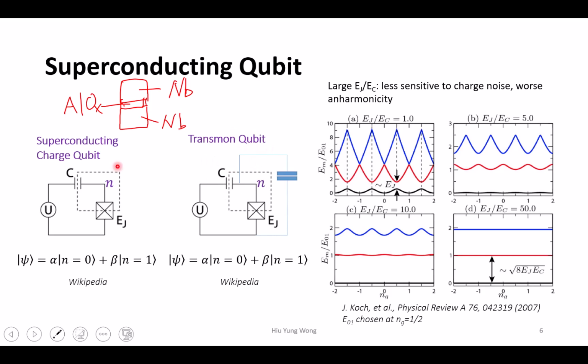What is Transmon? Transmon is basically just like a regular, what we call the Cooper pair box, the so-called CPB. Right, this is a box in which we can put Cooper pairs, but we just add very large resistance, very large shunting capacitor. So what is the goal, right? We don't really understand this figure at this moment. We will learn it. But basically, here on the x-axis is something called the background charge, Ng. I just told you that before we put any extra electron or Cooper pairs, you should already have a background charge, right? Depends on your setup.